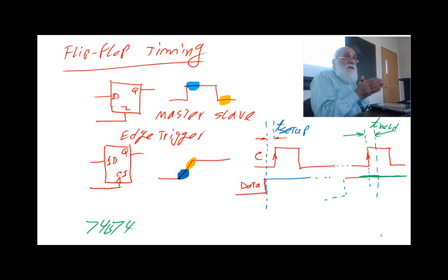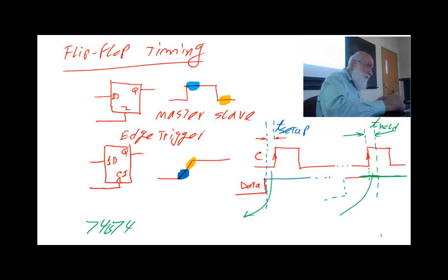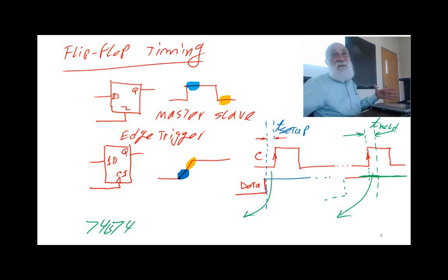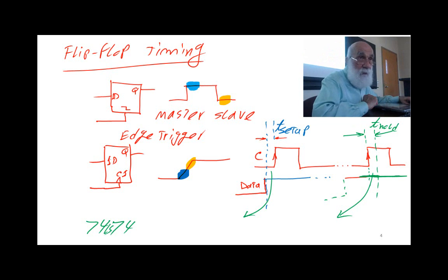See, these are not real. These are actually, you cannot extract it from the transistors and all that. These are experimental. Okay? It says that allow this much of time for the setup time and allow this much of time for the hold time. And therefore, when you buy a new flip-flop, it gives you actually several different things. It says clock frequency cannot be faster than this. Setup time is this. Hold time is this. Okay? And you have to follow this if you want your flip-flop to work properly.